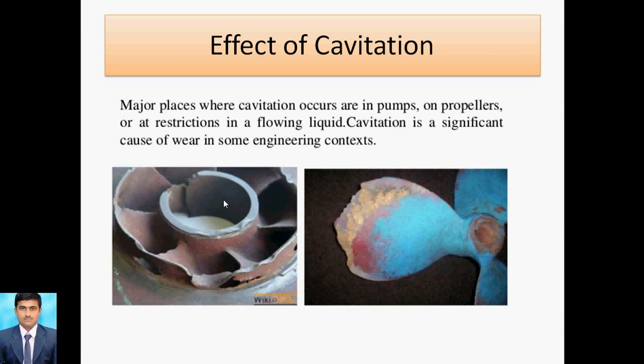This effect is reduced by two methods. By increasing the external pressure, the effect will be minimized, and we can also decrease the vapor pressure. If you decrease the vapor pressure, automatically the cavitation effect will be negligible. So this is regarding the effect of cavitation.